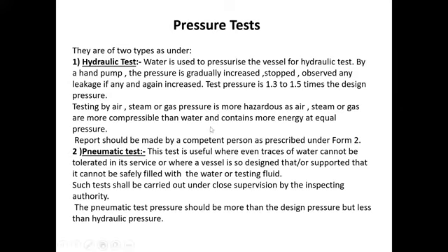The pneumatic test is useful where even traces of water can't be tolerated in service, or where the vessel is so designed or supported that it can't be safely filled with water. So if water is not feasible in that pressure vessel, only then do we go for the pneumatic test. The pneumatic test pressure should be more than the design pressure but less than the hydraulic test pressure, generally between 1.1 and 1.3.